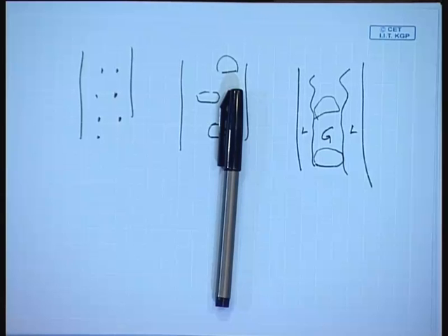Now, let us see under which circumstances we cannot use it at all, even if the two phases are completely mixed with one another. I agree, but it is flowing, maybe through an orifice or a very short nozzle. Under that circumstance, what do you expect is going to happen? Orifice means an abrupt contraction. Then what is going to happen? Rapid acceleration will take place.